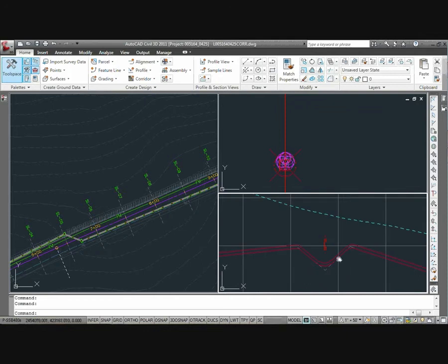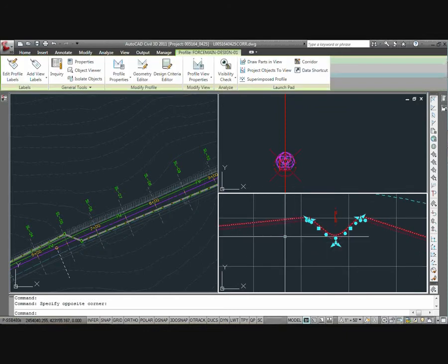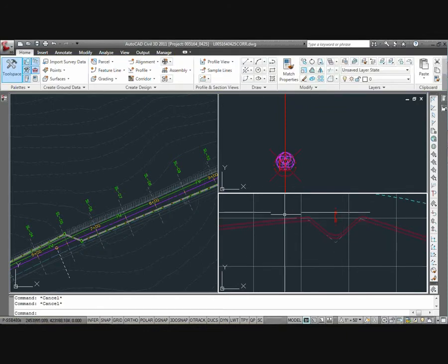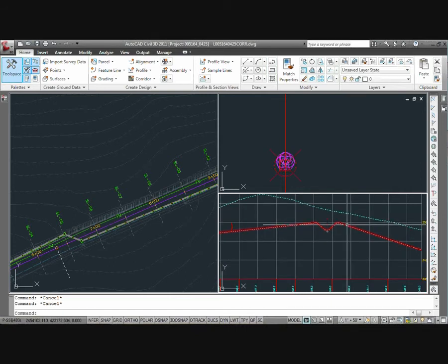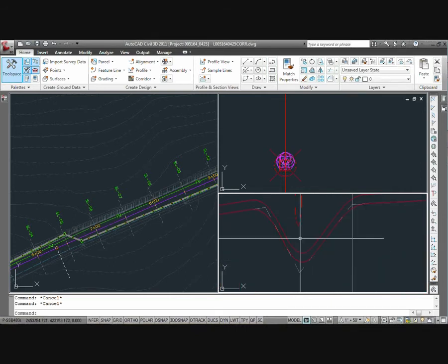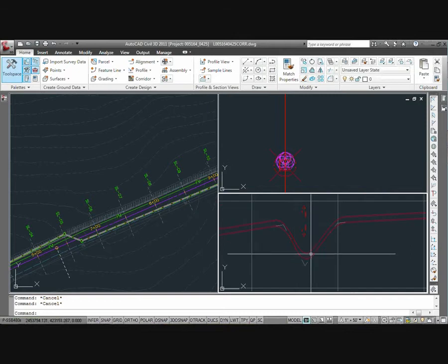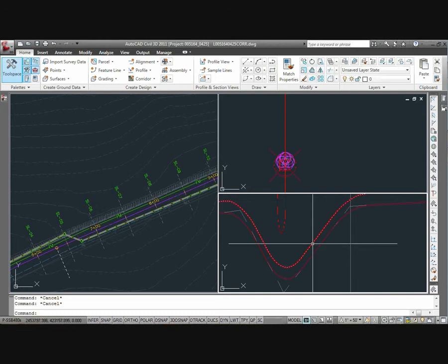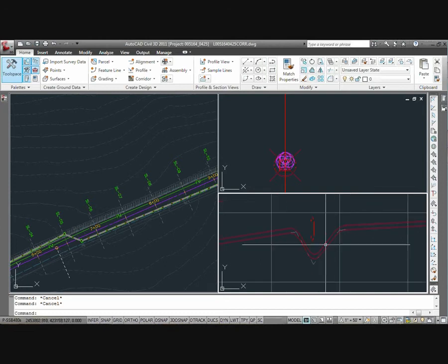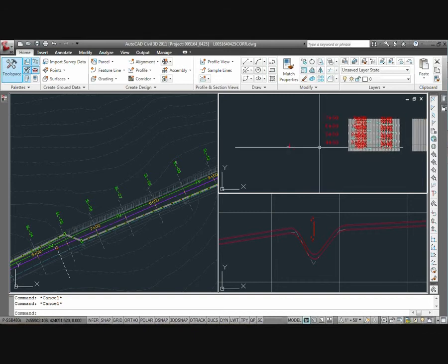And after that rebuild, you can see you can have a force main here, and you can show it in your design coming up and sliding underneath utilities and so on and so forth. So I find this funny. A lot of people will design this in by hand, and then they'll just offset the line up to be the top of the line when they're doing it by hand. That's not actually right, because it gets thinner here as you go steeper because of your exaggeration on your profile. So I've been drawing it wrong for years.